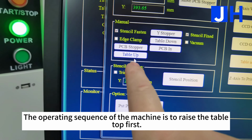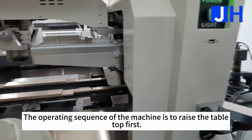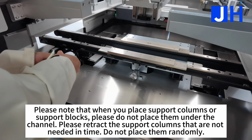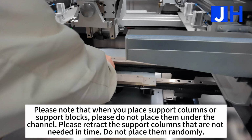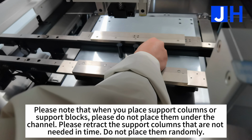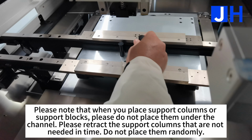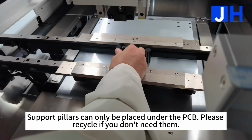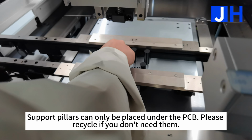The operating sequence of the machine is to raise the tabletop first. Please note that when you place support columns or support blocks, please do not place them under the channel. Please retract the support columns that are not needed in time. Do not place them randomly. Support pillars can only be placed under the PCB. Please recycle if you don't need them.